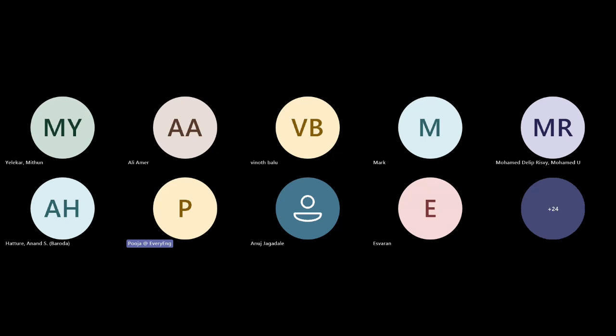It is the pressure and the temperature at which we want to design our plant. So as I said, if I want to select the thickness of a pipe, at what pressure and what temperature should I design those pipes or the component? I should have some values. The values on which this is designed are called the design temperature and design pressure. These are the highest temperature and the highest pressure that will be seen by that fluid.